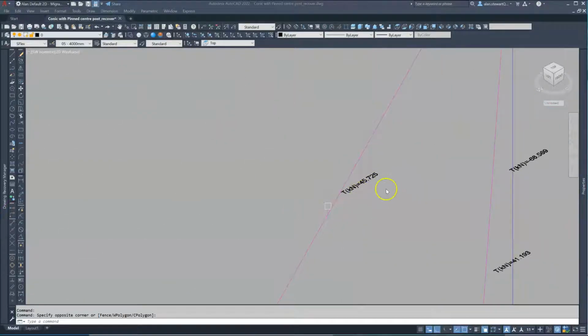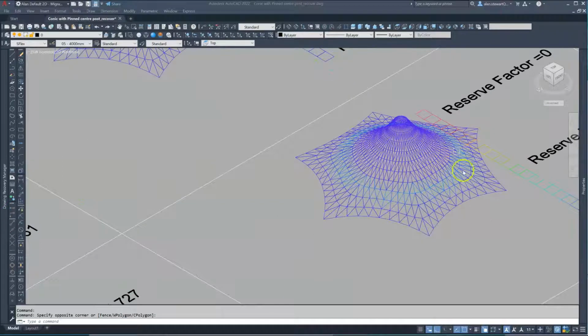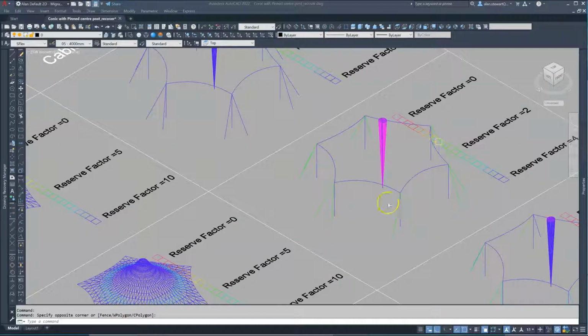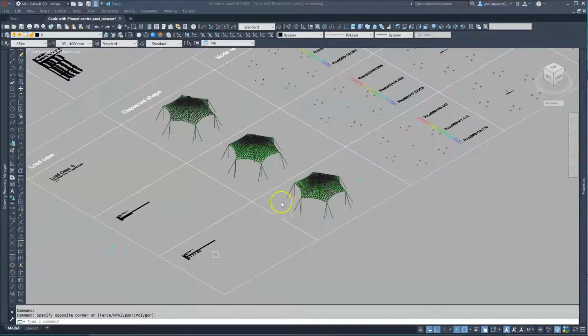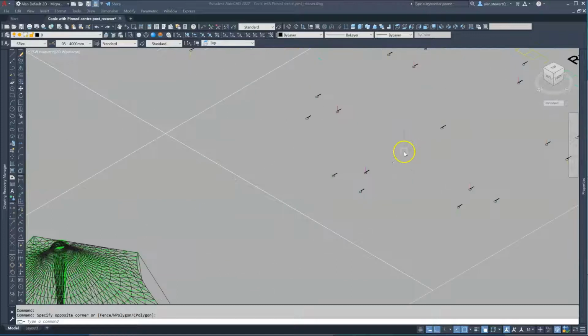There's the backstay cables. You can see a bit more stress in the fabric around the mid area, and we can see the reserve factor in the backstay cables with the cables that we used now down to a safety factor of 2. So again, we probably review the size of the cables and rerun the models with bigger cables for the backstays. Now in load case 2, we've got a windward load and a leeward load, so pressure down and pressure up, and here we can see